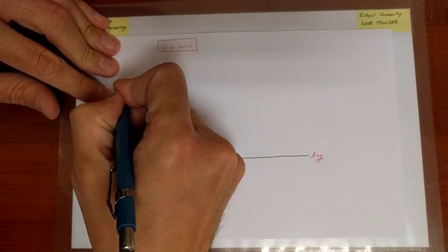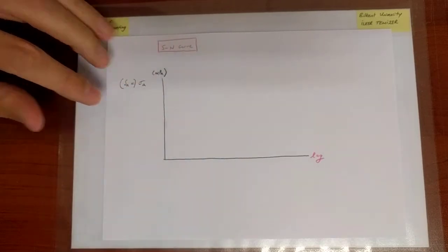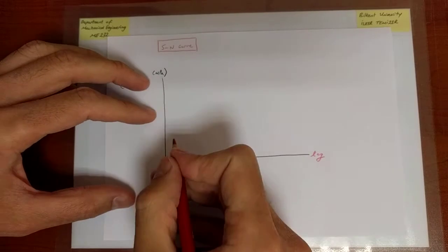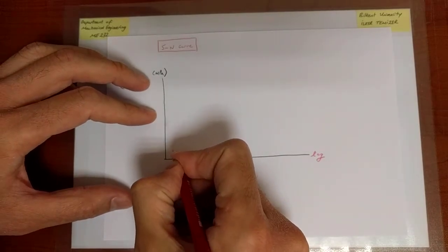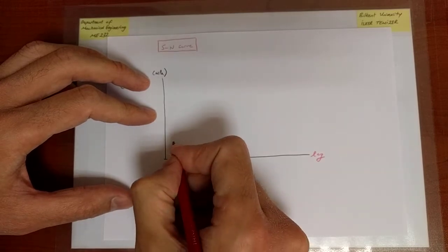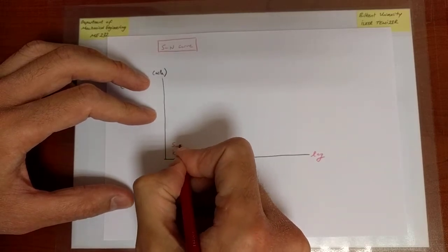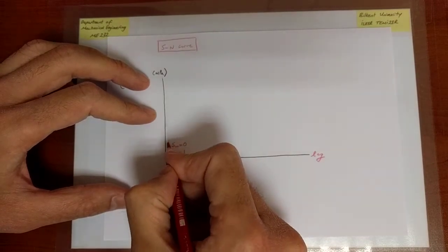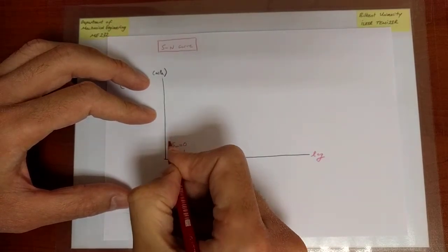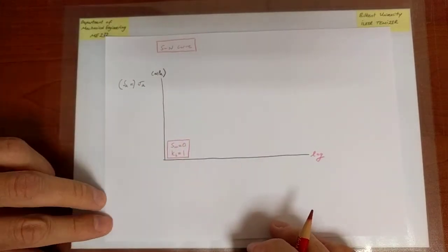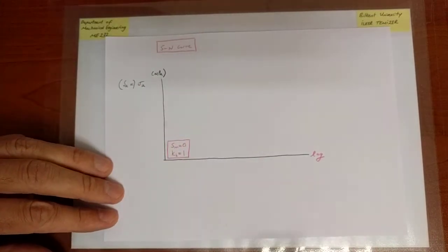to be equal to the nominal stress, because presently we're looking at a case where the stress concentration is 0 or the stress concentration factor is 1, and remember, we're looking at completely reverse loading, so it's important to keep in mind that the mean of the stress is also equal to 0. Sigma m or Sm is equal to 0.